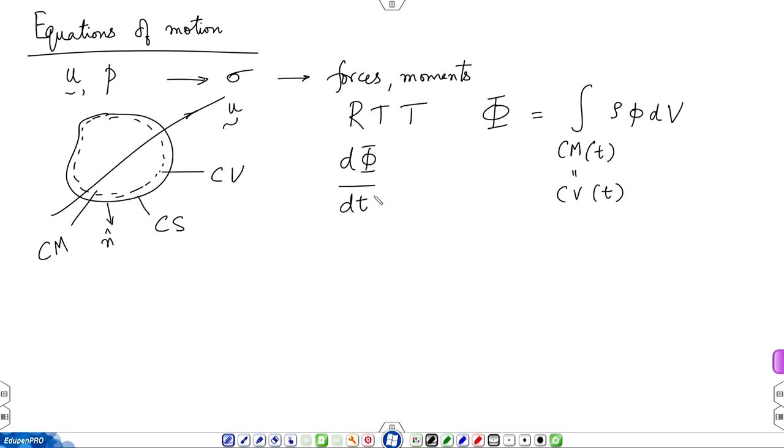So, when you say Cm t plus delta t, that is the material which has now gone out of Cv, that matter has gone out. So, how rapidly is it going out? It is going out at the speed u, the fluid speed u. Okay. So, every part of it is moving. Suppose you consider a small element here, it is ds, it is moving out at a speed u, where u is the local fluid velocity.